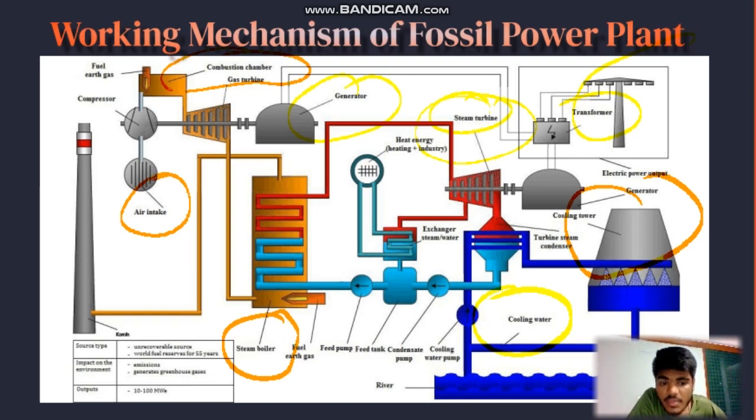In the cooling tower, the warm water from the cooling system is sent to the cooling tower, where it is sprayed or dripped down over a series of baffles that facilitates the exchange of heat with the air, gases, and causes the water to cool down. So this is the cooling tower which we discussed recently.